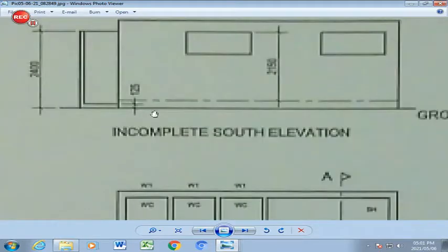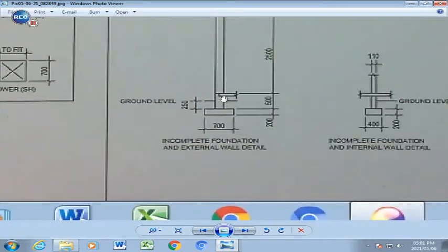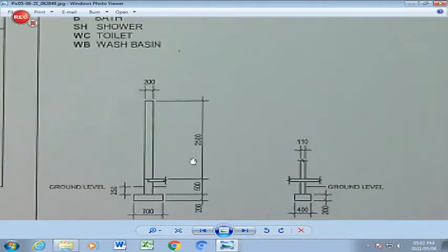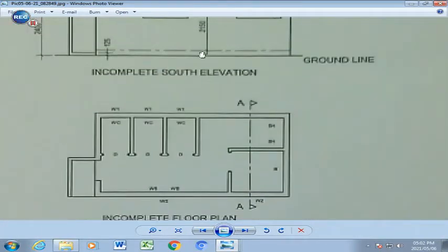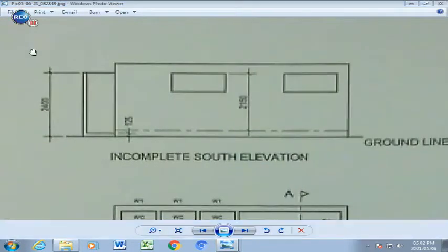Please take note of the floor level here, which you will see. And that floor level comes from this specific section that we will see here, that being the natural ground level, and that dimension that you see here deducted from the 500, which is 250, and of course divided by 50, which will give you the floor level that you have there. Also take note of where the dimension line strikes for you to be able to get correct dimensions. Let's proceed to complete the south elevation.